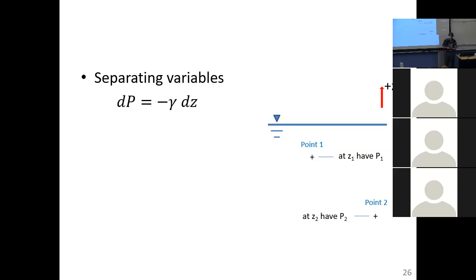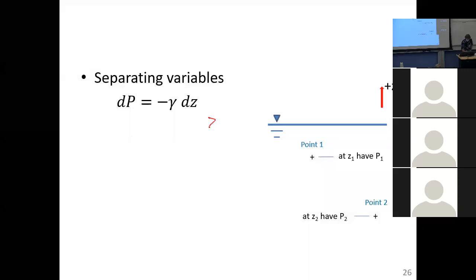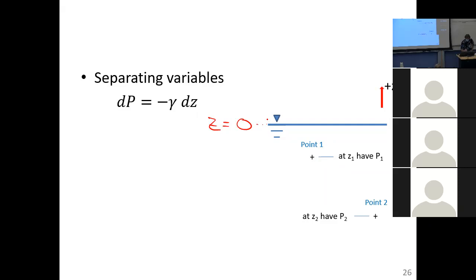In all of your problems for me, you will do that. So for example, you could say that at that interface, that's where I'm going to have my vertical coordinate axis datum. Z is equal to 0 feet, 0 meters. It could be a local elevation datum. It could be an internationally recognized elevation datum.